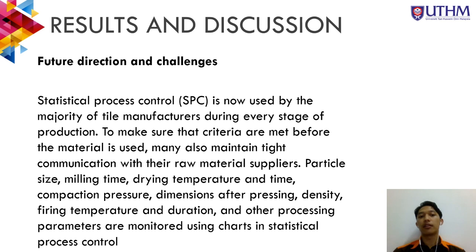Many also maintain tight communication with their raw material suppliers. Particle size, milling time, drying temperature and time, compact pressure, dimensions of the pressing, density, firing temperature and duration, and other processing parameters are monitored using charts and statistical process control. With that, I end my presentation. Thank you.